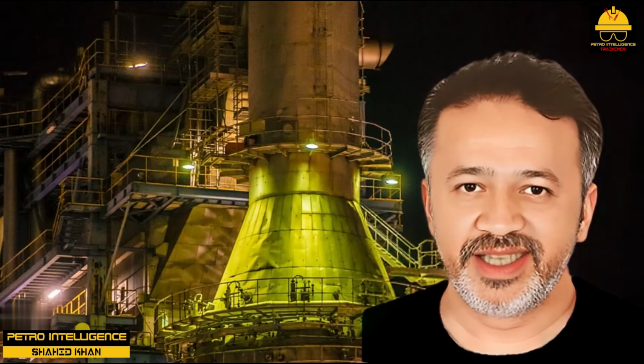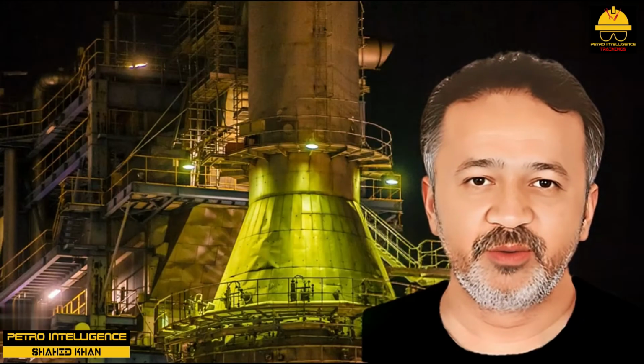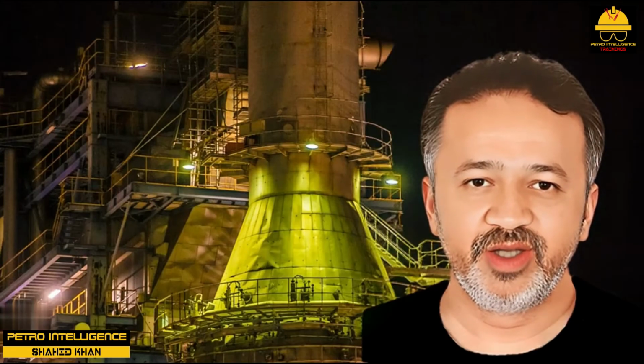Do not stand directly in front of an inspection port while you open it, in case there is positive pressure behind it. Flame color depends on fuel composition. Gas often burns blue, but heavy fuel oil burns yellow. A yellow flame is caused by thermal cracking of the fuel.